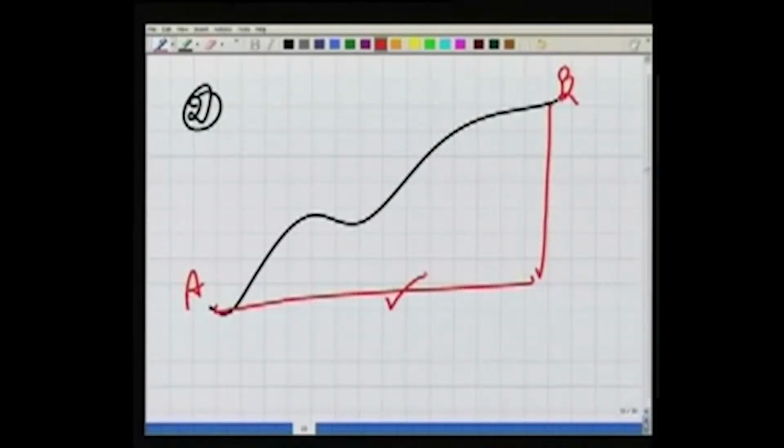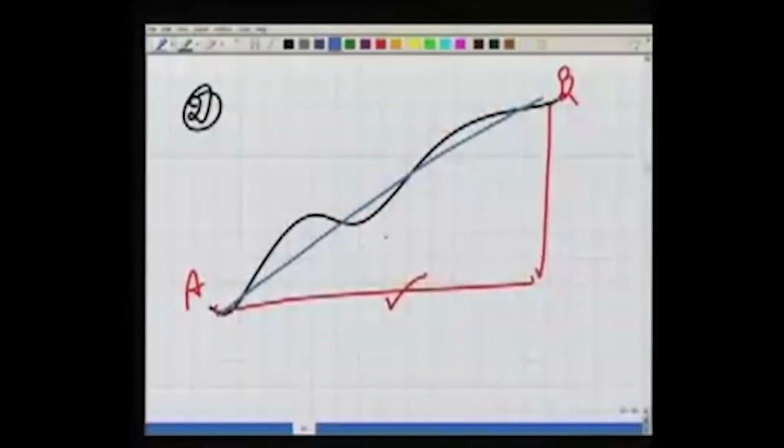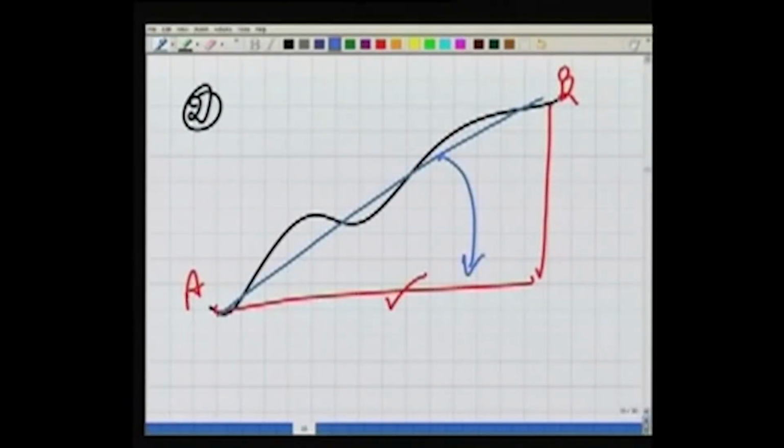We don't measure the angles in a sloping plane, rather we measure the angles always in a horizontal plane. And this is how the theodolite is made. So directly, by the computations, we compute the horizontal length. But in the case of trilateration, we are measuring the sloping distances. So this sloping distance which has been measured needs to be finally reduced to its horizontal component.